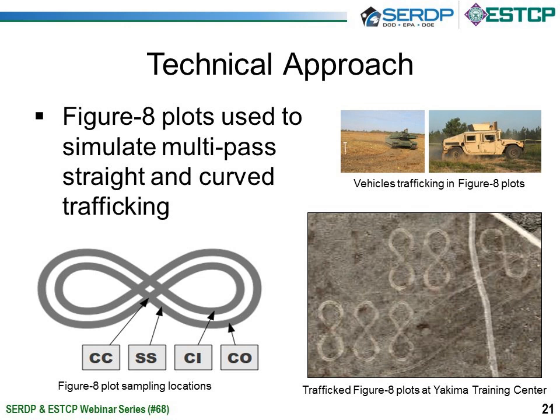The vehicles were driven in figure-8 patterns in cumulative sets of passes to represent roughly a low, medium, and high level of disturbance. 1 or 2 soil types were trafficked at each site in 3 replications for each vehicle-soil combination. After each set of passes, measurements were made and samples extracted for later laboratory analysis to characterize the surface susceptibility to wind erosion and potential emissions of fine particulates.